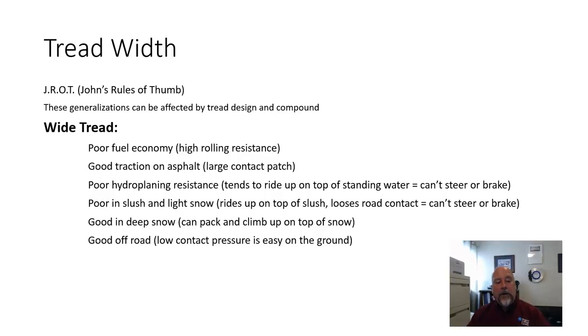Okay, so wide tread. Poor fuel economy because you have a higher rolling resistance. There's more rubber flexing in contact with the ground. You tend to have better traction though because you have a wider, bigger contact patch. Poor hydroplaning resistance.